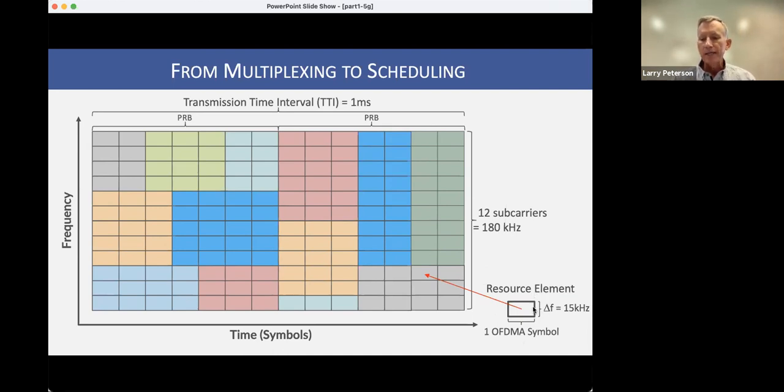And so basically I'm allocating these little time units, and this particular set of numbers comes from 4G, where there wasn't so much flexibility, but in this given time unit, I can transmit one symbol, and that might be 4 bits, it might be 6 bits, but I can transmit that symbol using 15 kilohertz of the spectrum and 1 unit of time.